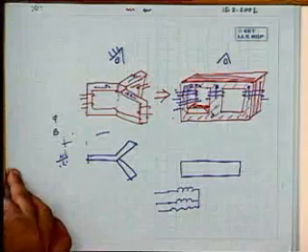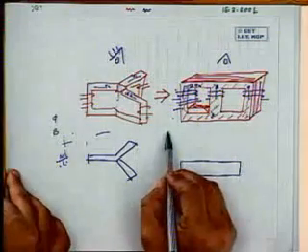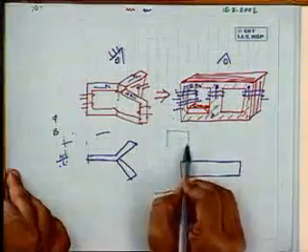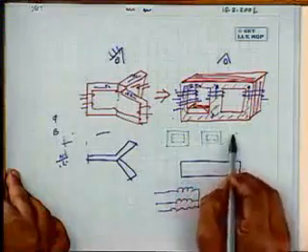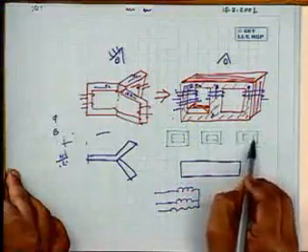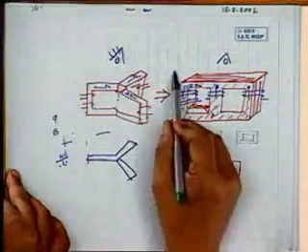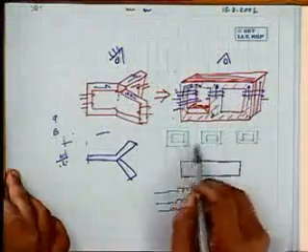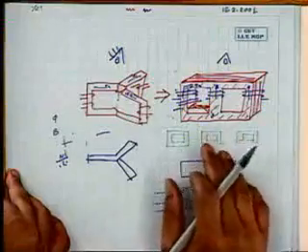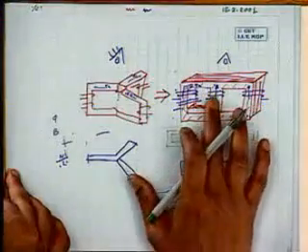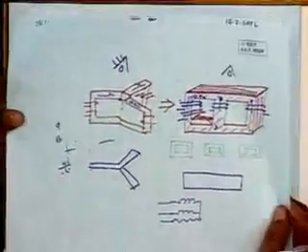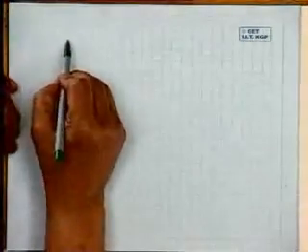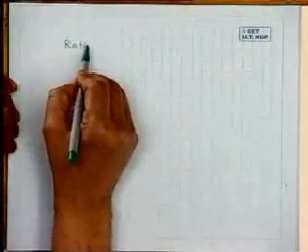Now, the important point I would like to come to. So, I can have a 3-phase transformer by using 3 single-phase units, that is a bank of 3-phase transformer, like this. And I can have a 3-phase unit transformer as a whole. This, I think, is now clear to you why it is called a bank of 3-phase transformer and a single 3-phase transformer. Now, how the rating of a three-phase transformer is given, first I will tell that.